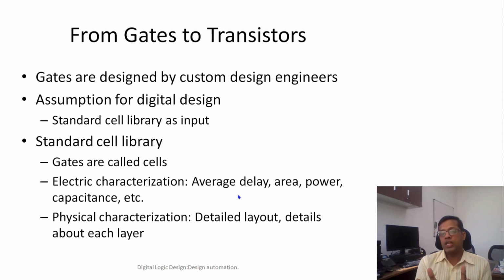All those electrical details are present to us in some abstracted manner, so that whenever we analyze using the standard cell library, assuming this input, we can have some estimation of what the overall latency is going to be, or the minimum or maximum latency for our design. Then we can calculate the clock period, so that we can say how much design could fit in one clock period.